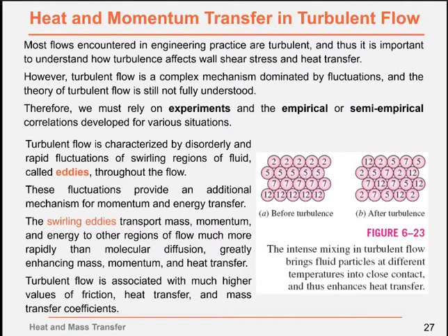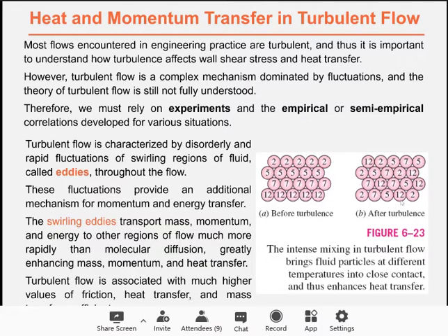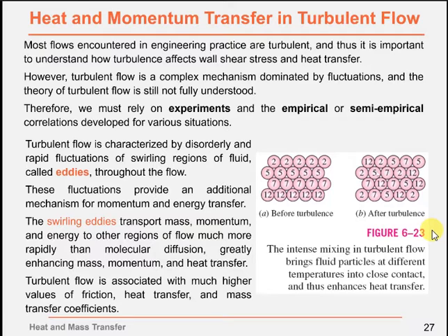You can see before turbulence, the particles lie in different layers, and after turbulence, the particles from different layers go to other random places, so they contact each other and exchange heat, which enhances the heat transfer.